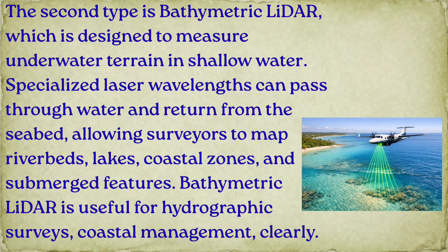The second type is bathymetric LiDAR, which is designed to measure underwater terrain in shallow water. Specialized laser wavelengths can pass through water and return from the seabed, allowing surveyors to map riverbeds, lakes, coastal zones, and submerged features. Bathymetric LiDAR is useful for hydrographic surveys and coastal management.